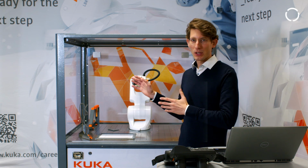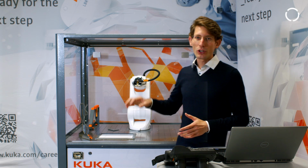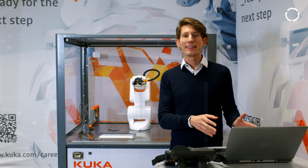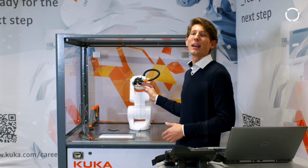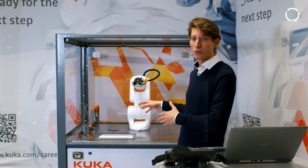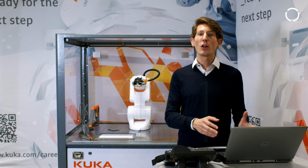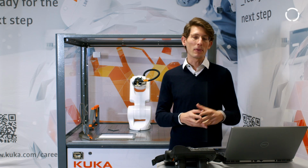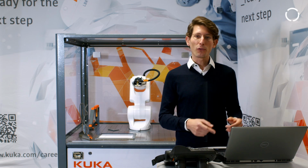I want to show you how you can transfer programs from KUKA.Sim to a real robot. In this use case we have the Ready to Educate cell and we're going to write a little offline program in KUKA.Sim and then transfer it to the real robot, the KR4 here. Then we change some points or the program a little bit on the real robot with our touchpad and then transfer it back to KUKA.Sim to have the most updated version of this program in our simulation tool. Let's get started with the offline programming.